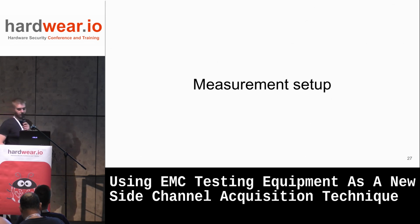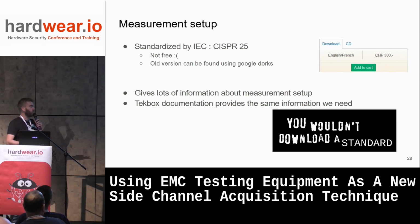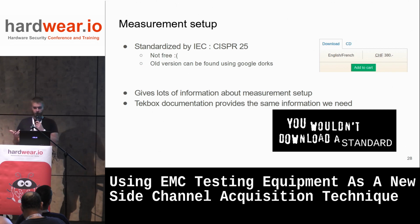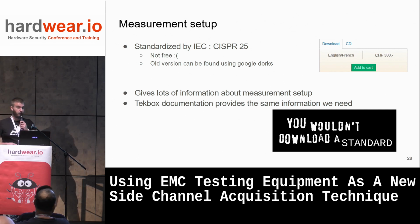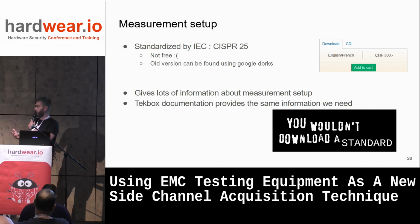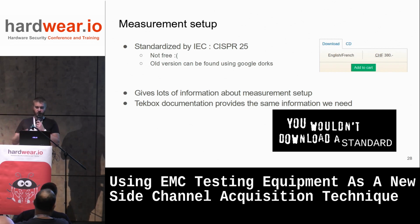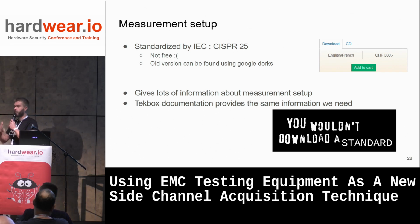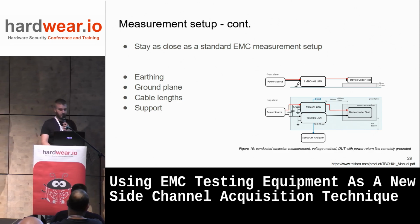Okay, so now that we have a device for measurements, how does it work, or how do you make it work in a setup? There's a standard, CISPR 25, which is unfortunately not free. You can still find some versions of this documentation using Google, but you can also find this documentation for other LISNs in the user manuals of those LISNs. They give you information about how to use those, and it usually looks like this.